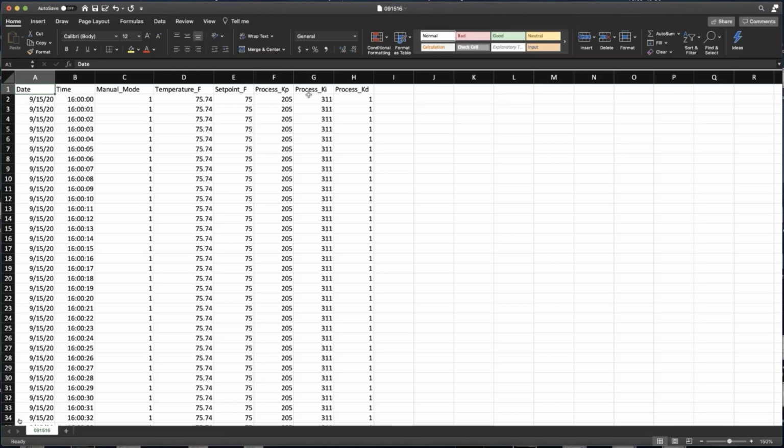You'll see the very first log was at the very top of the hour, because keep in mind, we're logging data every second, and effectively the OCS is automatically going to create a new file at the top of every hour. Now there's a couple exceptions to that. When I first enabled data logging, which in my case was when I downloaded the program and made sure it was in run mode, it will immediately start data logging from that point. So let's say it was 5 or 6 minutes after the top of the hour, or really any time during the hour, it'll just immediately start at that point, and then it'll finish at the end of the hour. And then the next log will start at the top of the hour.